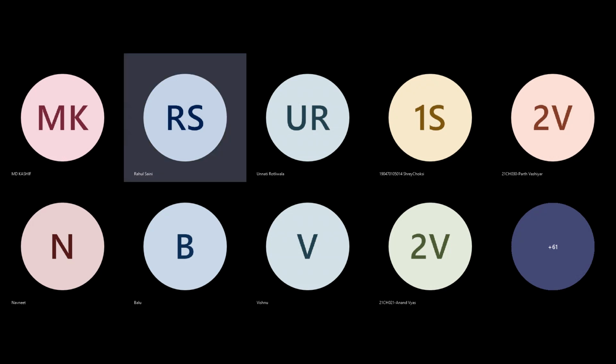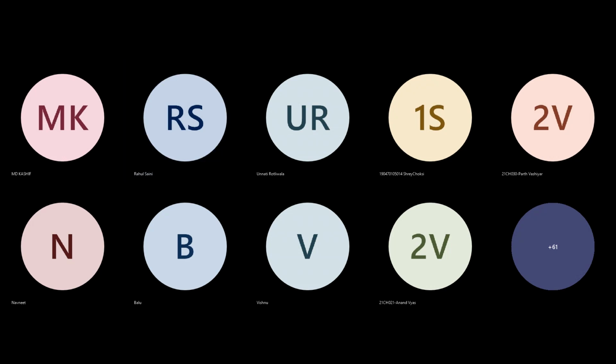Okay. Other questions? One thing, what is the F factor we are using? It is the friction factor. There are two methods, Moody friction and Fanning friction. Which has to be used? The Moody chart is basic. The friction factor F here is the Fanning friction factor. It is calculated from an equation, and the Moody chart is basically a graphical method. Nearly both are the same. For our case, we have considered the Fanning friction factor. So one is a graphical interpretation and one is an empirical equation, right? Correct. There is no difference between both.